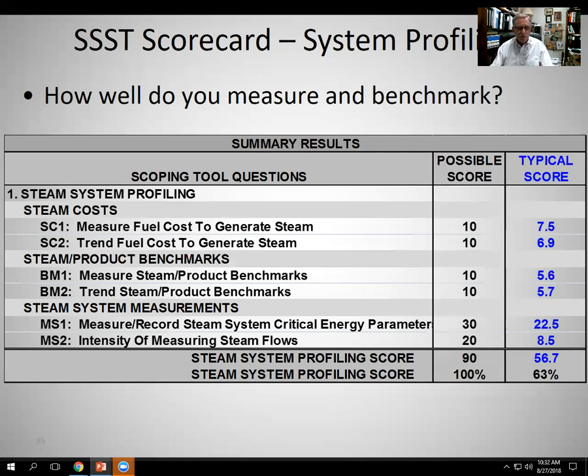But if you bring gas in and you split it 5 different ways, and one line goes to the boiler, but the other 4 go to other types of gas-consuming equipment, then you really don't know what portion of your total bill goes to the boiler. And so that would then indicate, well, maybe we should put a meter on the boiler. So then we do know, and we can quantify, and we can get some hard data on how much gas we're burning in order to produce steam.